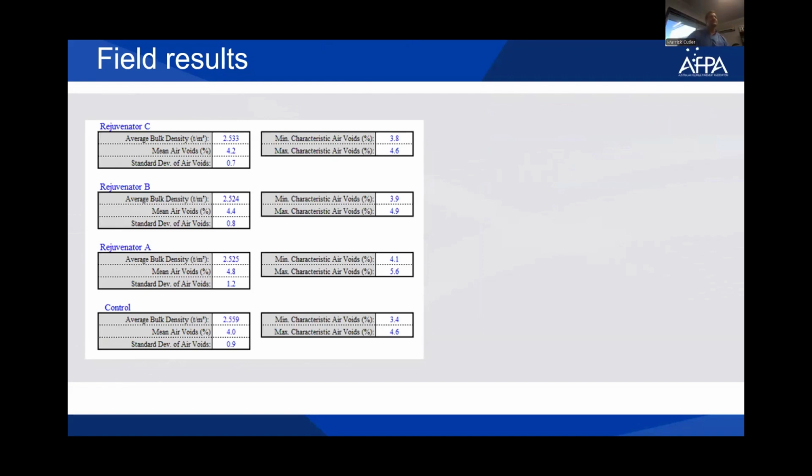What I will say too is that part of the distress of this particular road is we actually profiled out and put in a layer of EME first, obviously to give it that structural integrity. And then there was a tack coat that we went on before we did the wearing course at 50 mil.